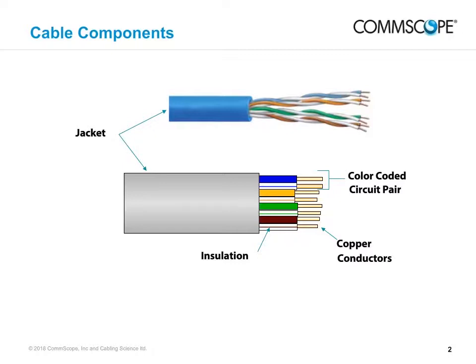This usually consists of two strands of copper wire measuring between 22 and 24 on the American wire gauge, which are insulated and twisted together. The twist is vital to their performance. The two wires follow helical paths with opposite directions of rotation. This allows any stray signals induced in the conductors to cancel each other out. So the transmitted signal entering one end of the cable arrives at the receiver without being distorted by stray signals.